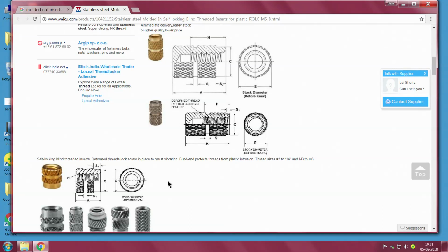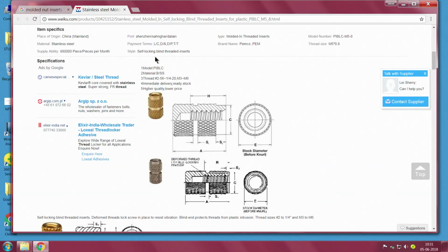Can we use it in our rapid prototyping? No, because we still have an issue: as we build layers, in case we put this insert there, it will get in the way of the nozzle, and if you try to push the insert in after it is made, chances are it will not go well. It does not sit well because the material is not a free flowing material like fully molded plastic, especially glass filled nylon or aluminum. So we have to look into some workarounds.